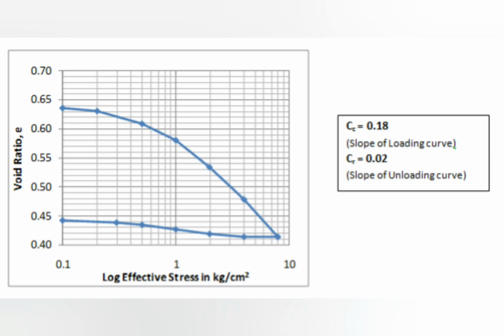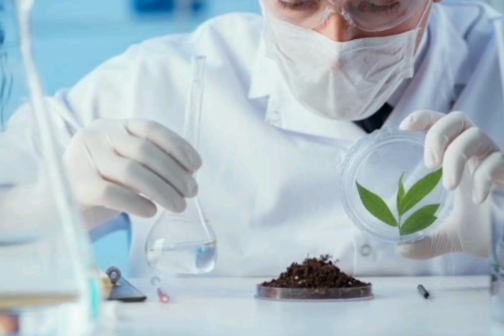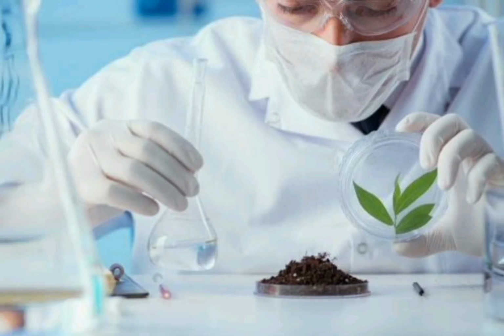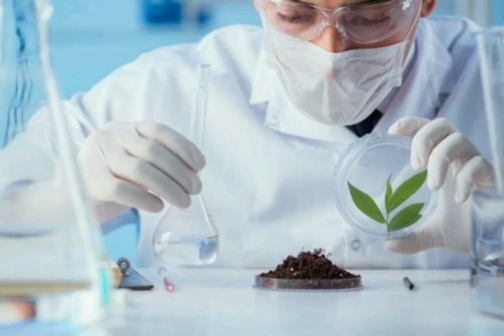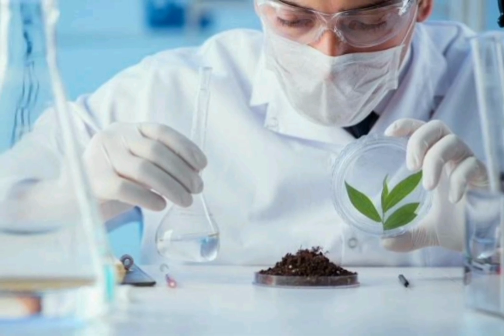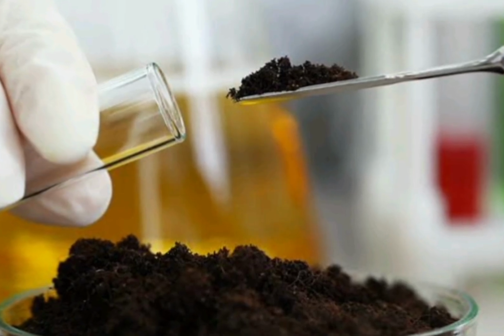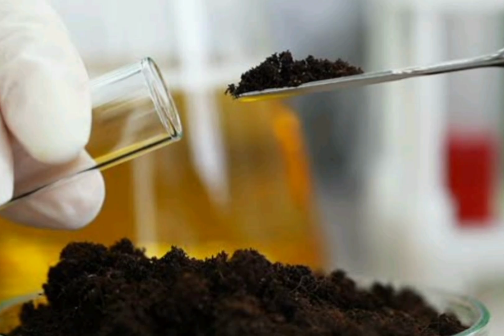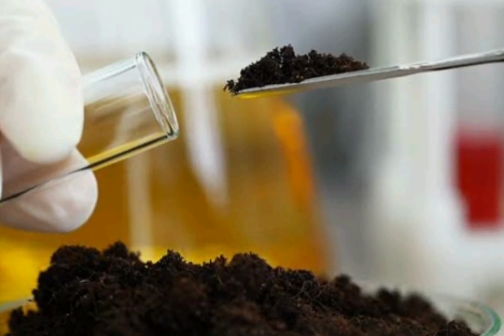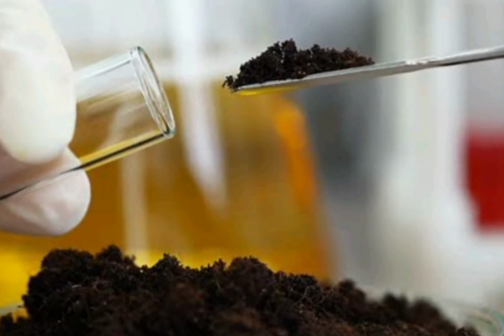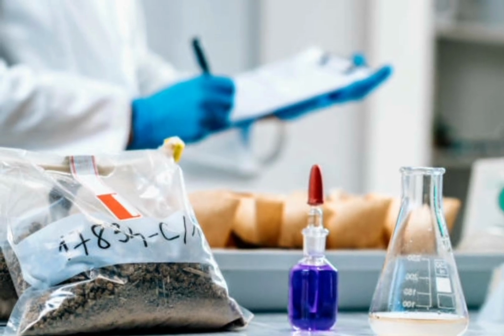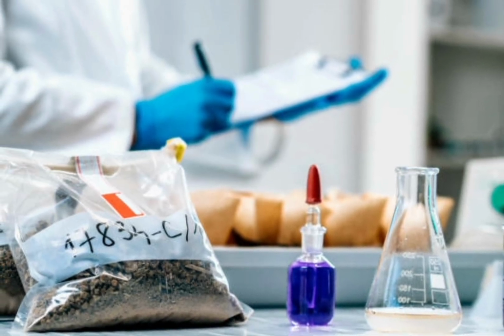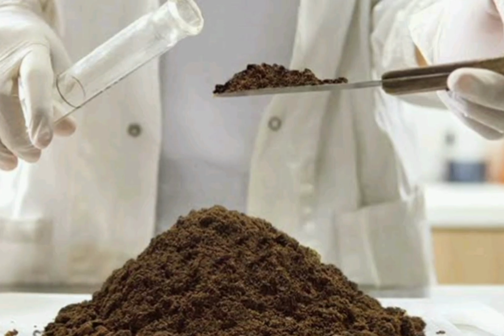In conclusion, laboratory soil testing transforms soil from a mysterious, variable material into a quantifiable engineering material with known properties. The classification tests tell us what it is, the compaction test tells us how to densify it, the shear test tells us how strong it is, and the consolidation test tells us how it will settle over time. This data is not just for a report that sits on a shelf. It is the direct input for every geotechnical design decision, from the depth of your footing to the slope of your excavation. It is the difference between building on a known foundation and building on a hope.